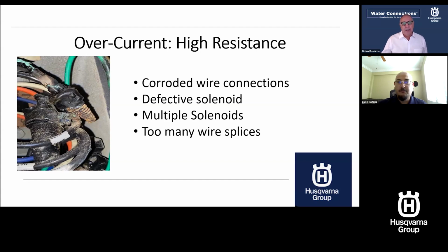So in that case, my valves are going to work or not? Generally, they're not going to work, Richard. If you have a smart controller, it's smart enough to know that there's too much power going through there. In the case of our ET water controllers, it shuts off and protects itself. So we'll protect the controller and the watering stops. So, for example, say your controller waters a dozen stations and it's going 1, 2, 3, 4, 5, and that station 5 has an overcurrent. Your controller powers off, suspends, sends an alert for overcurrent, and then your stations 6 through 12 would not have received any watering.